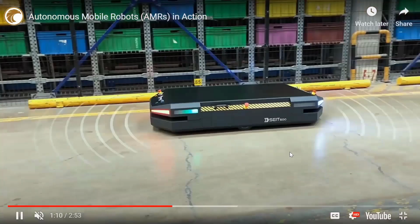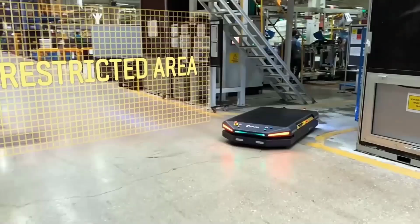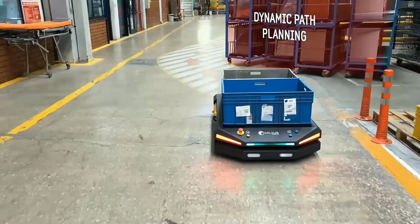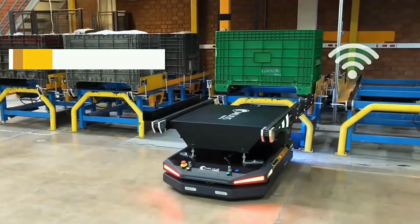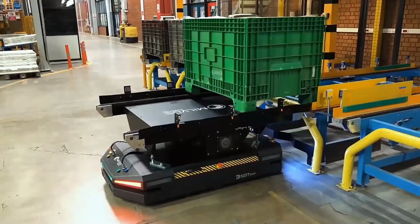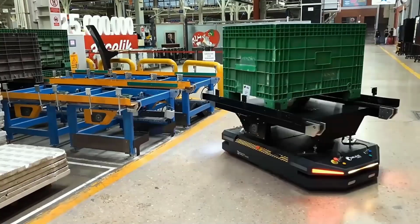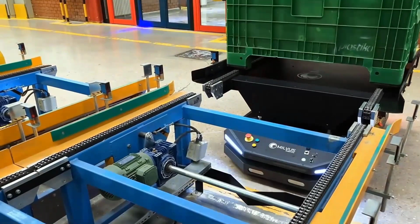So we have these sensors that are looking for obstacles, and also to say, okay, whether it's a restricted area. Generally, this is the job of the route planner on the top level, to not enter the restricted areas, and also to look for pedestrians, which is the same as autonomous driving, and also to change the course of action if there is an unexpected environment, etc. And also localization here. The localization is also very important because we should be able to pick the boxes or something very efficiently, because these are of exact dimensions and we should be moving them in the same way.